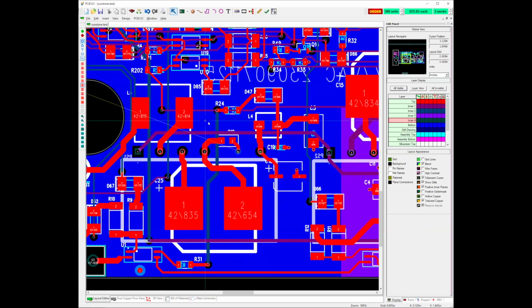Can we use Snap EDA to check the part? Sure, but Snap EDA is not necessarily going to tell you if the parts are available and easy to find. But you can take those, save them to a spreadsheet, and take each line item and copy it to a search window in DigiKey or Mouser or any of those companies, and it will tell you if those are obsolete or not. They'll either find it or not. And so it's pretty quick and easy to do that.